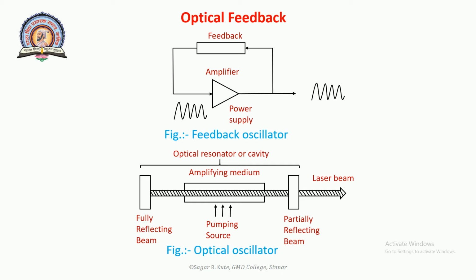The input is amplified and the output is fed back to the input, where it undergoes further amplification. The process continues until a large output is produced. Saturation of the amplifier gain limits further growth of the signal and the system reaches a steady state in which an output signal is created at the frequency of the resonant amplifier.